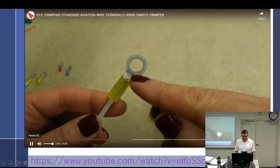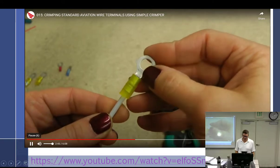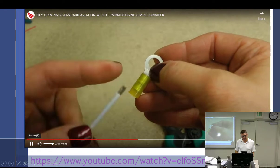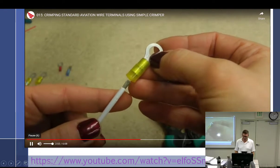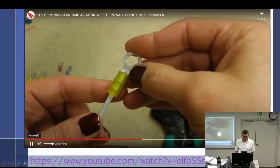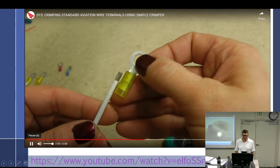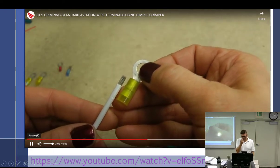So keep that right at the edge. It won't go any further with this length because you'll see a groove right in the center of the barrel here, and it is catching the insulation there, so it won't go any further through. And that's about what you want to see when you strip the wire back for your connection here.